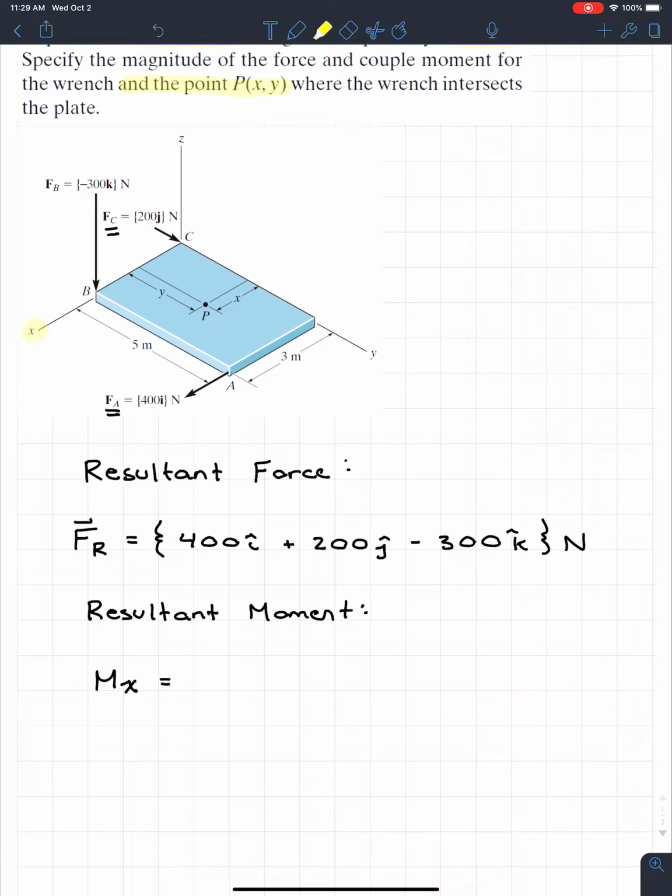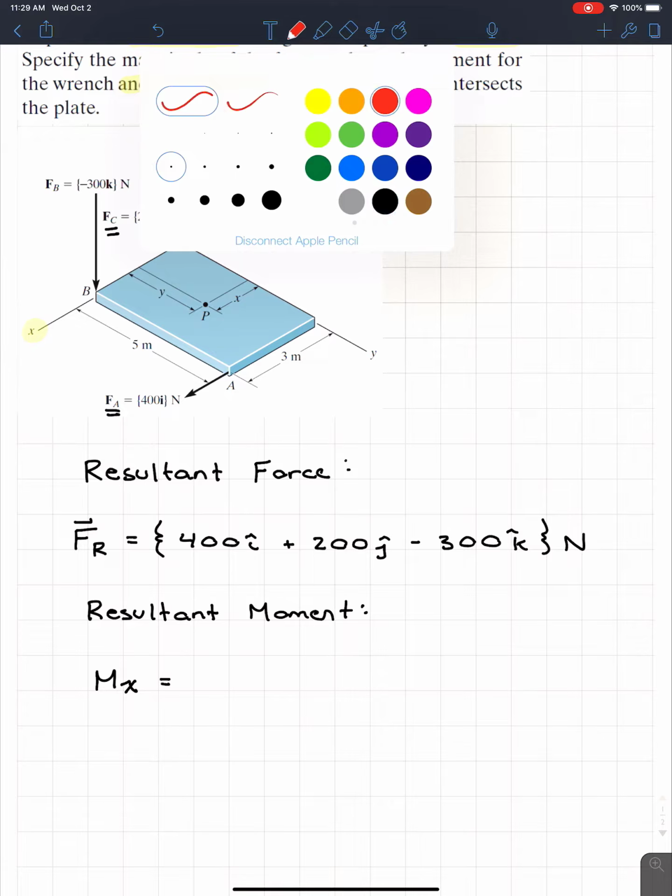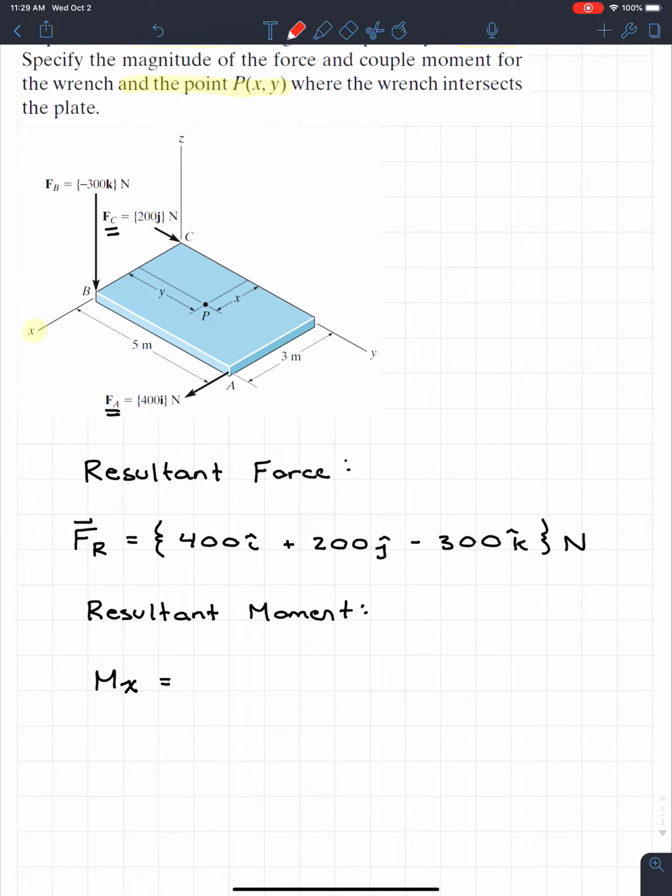Because there's a couple criteria that creates a moment. One is if a force, and I'll go to red here so we can cross them off, remember, to create a moment about that axis, the force has to be perpendicular in that plane. So if we look at Fa really quick, we know that that won't create a moment. So we're going to get rid of Fa. If we look at Fb, well, that is perpendicular in the plane, so that would create a moment. However, that force intercepts the x-axis, so that distance, that moment arm, will be 0. So Fb also does not create a moment.